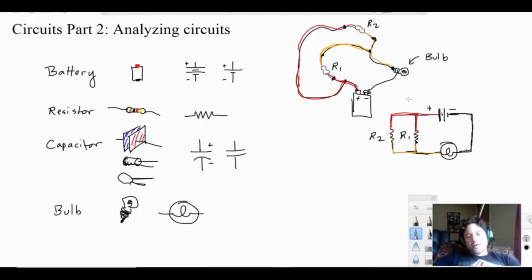One last note before I go on to the next video. Each of these colors is not just a theoretical color, it actually represents something important: voltage. We know, since this is, let's say, a 9-volt battery, that the red, touching the positive terminal, represents 9 volts, or whatever that terminal happens to be, right? If it's a perfect battery, and it's exactly a 9.0 volt battery, you would expect this red to be exactly 9.0 volts.